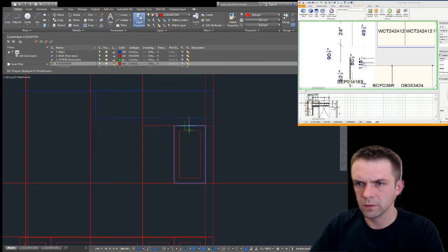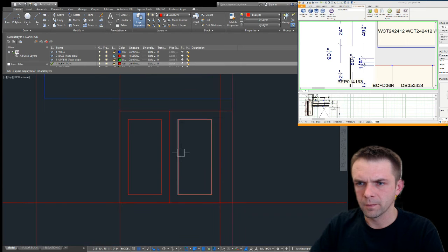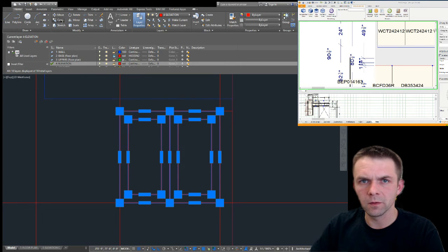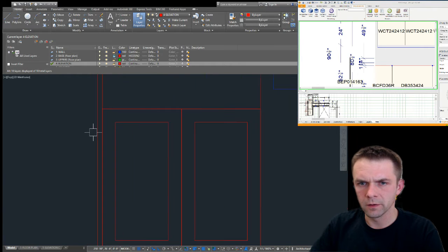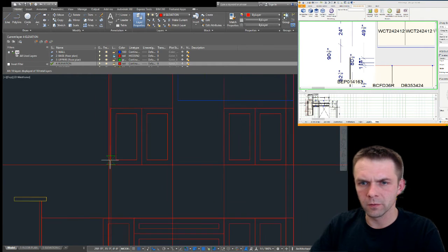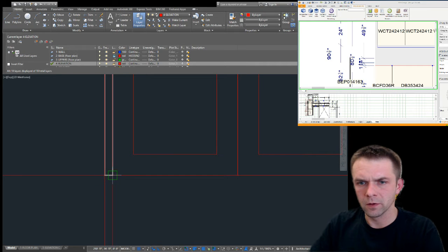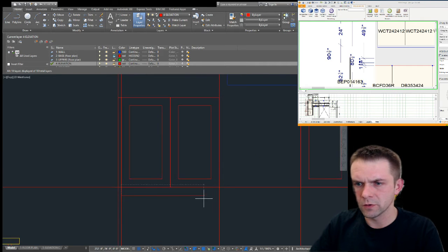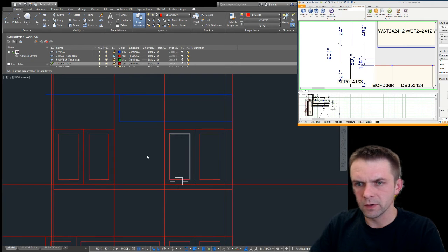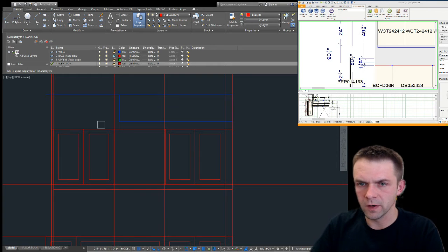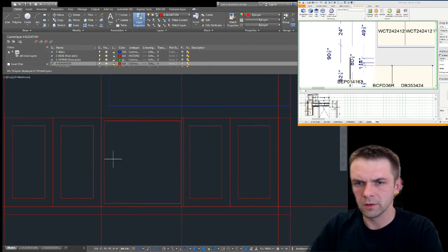Offset 2. And because it's the same, you can just copy, click, move it here. REC from here to here. Light valance 2 inches, and it goes all the way to here. We already have this rectangle, and this is just 0.75 open shelf.